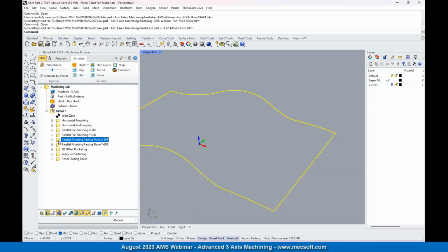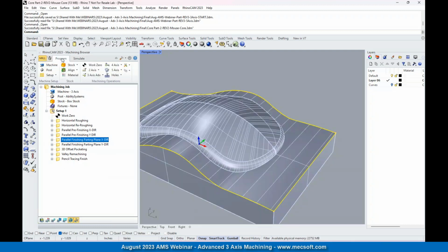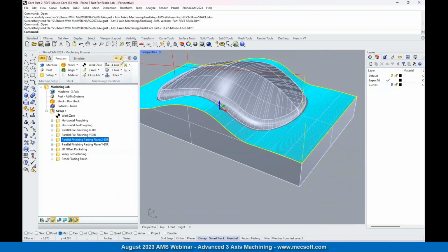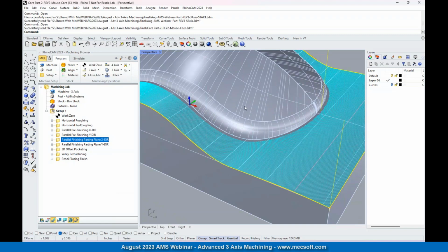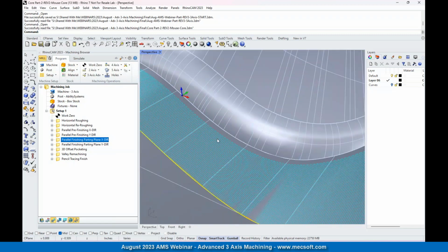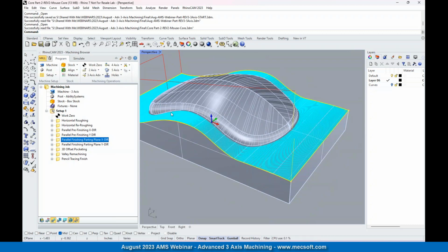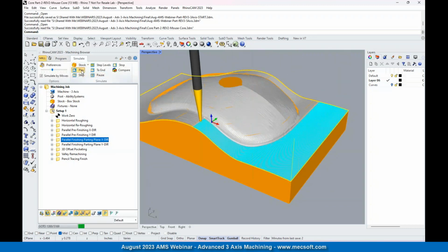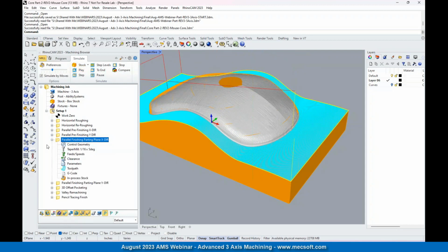So on this next one, we have our finishing operations for the actual parting plane right here. So we use 2 curves. I don't look like I have that curve displayed, but it just cut between these 2 curves, an inner curve and an outer curve. Let's go ahead and simulate that real quick. And again, I used a smaller taper mill with a smaller ball on it. I used a 5-degree taper mill, same draft, but with a 1/16 ball.